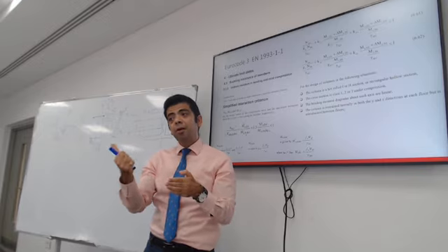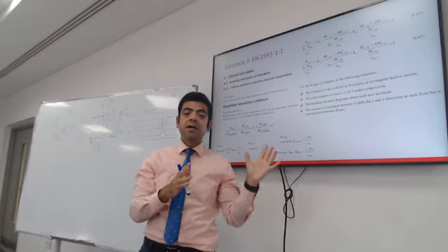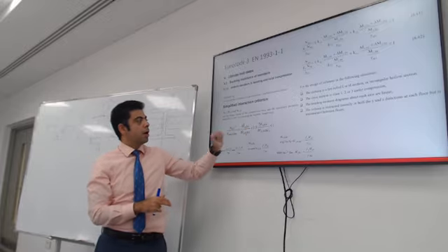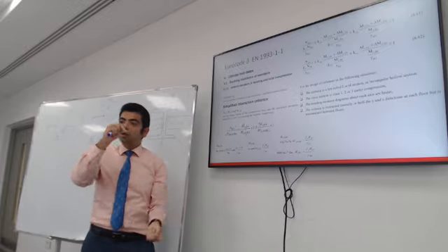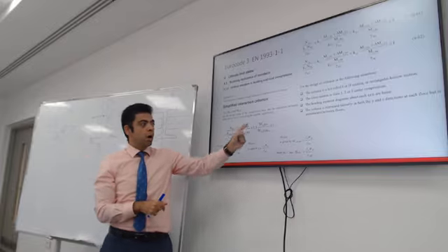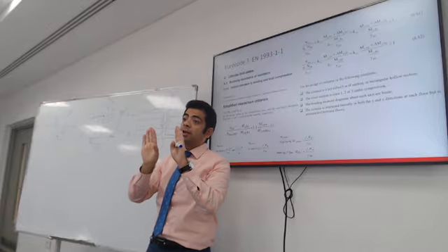You get the dead load and live load, and use the factors to design an ultimate limit state. So the factors on the top are the actual factored normal force, the moment in x and moment in y, or the axial load multiplied by the eccentricity from the connection.